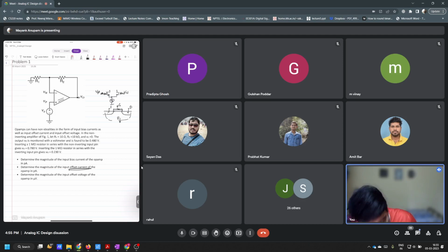So there is no direct connection between the gate, source and drain. In between them there is this oxide layer, which is an insulator, so there can be no current passing through directly. You can assume the current here is approximately equal to 0.